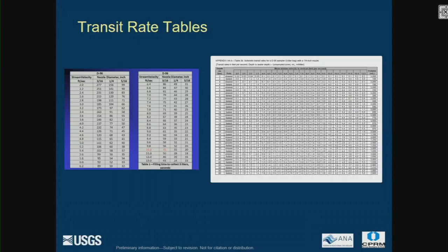Now, this table here is what our National Field Manual people, folks and groups have already hand computed. They've done the math for you. They give you the range of the efficiency triangle that you were showing the other day. These are all of those different transit rates, and it gives you a little bit more flexibility on the amount of water that you're collecting.